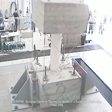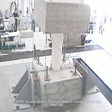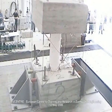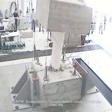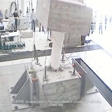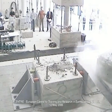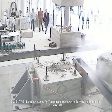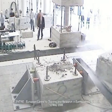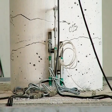Our goal in the DORII project is to set up a virtual and distributed lab for earthquake engineers, employing some basic instruments such as strain gauges to measure deformation, load cell to measure applied force, and an actuator to stress the specimen. In particular, all these devices are employed to create a force displacement diagram. That is, a force is applied to the specimen while reaction and deformation are recorded in order to tune a model of a concrete wall.